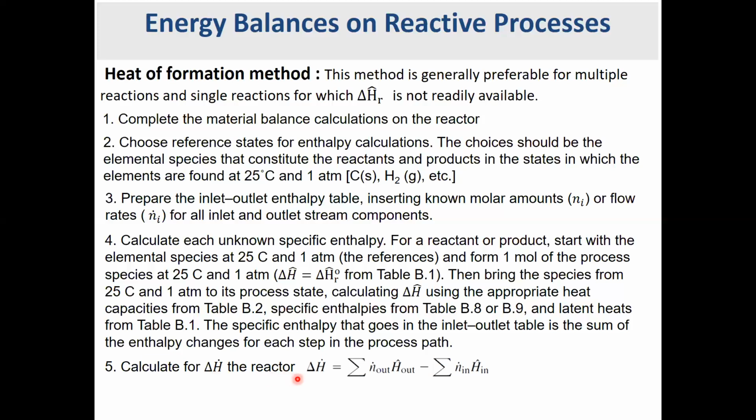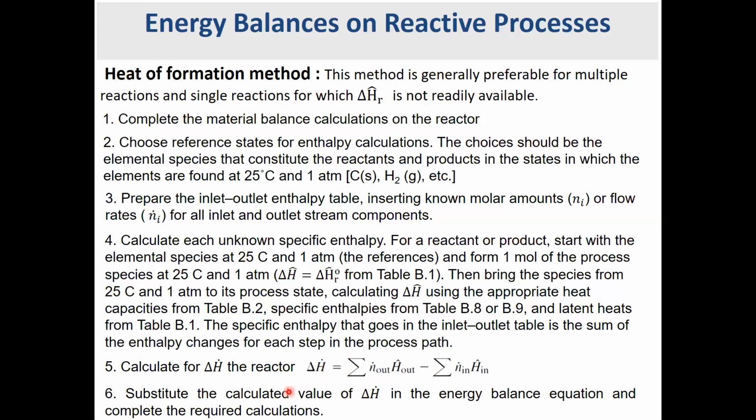the rate of enthalpy change. If you focus here, you will see we don't need a standard heat of reaction or heat of reaction in our calculation for the heat of formation method. That is why we use this method, because it's not our concerned value. And at the end, as you have the values of delta H, you can put them in the energy balance form and calculate what it is. If heat transfer or whatsoever you need, you can calculate.